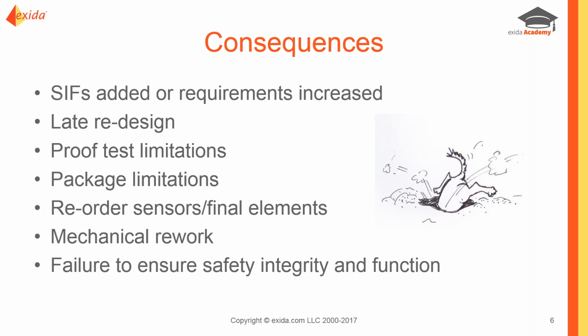Package systems, typically those that are vendor package systems, may come with their own PLC. They may interact or be part of your safety function trip. If those are identified early on, we have an ability to work with those package vendors and do some things that are more geared towards our reliability requirements and the SIF trips. If we find out later on that those packages are involved, then we're pretty much limited to whatever is in the package and may have to find mitigation or risk reduction elsewhere that we could have addressed with those packages.